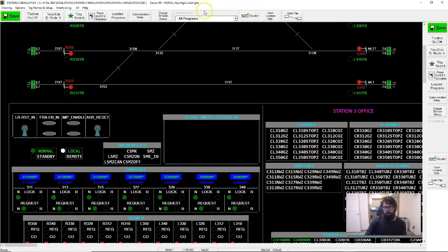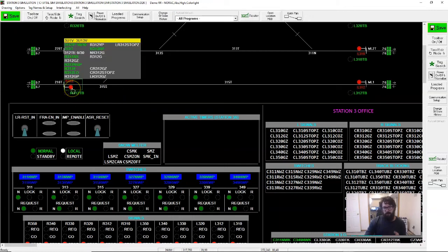Okay, now this is what we call the track plan, or the drawing, and in simulation terms, this would be the visualization or rendering layer or interaction layer. So we're not seeing the equations here that actually tell us what the controller is thinking, what outputs are moving, what states variables are in general. We're just seeing a physical representation of the site. Now, we can look at this and we can infer what's going on inside the controller, because all of these icons have been configured to render depending on the state of certain internal controller variables.